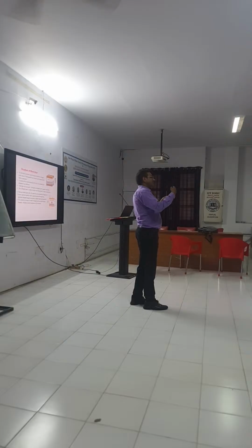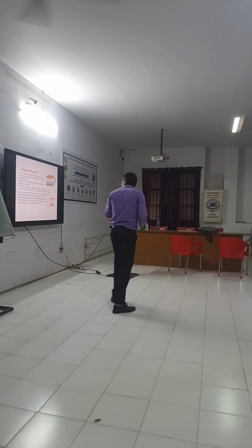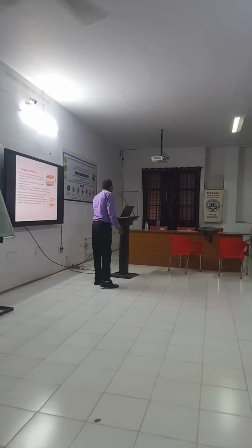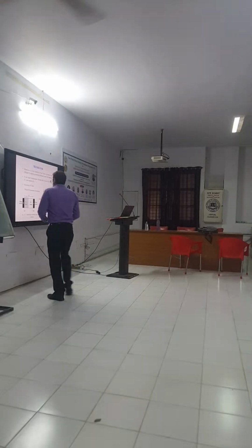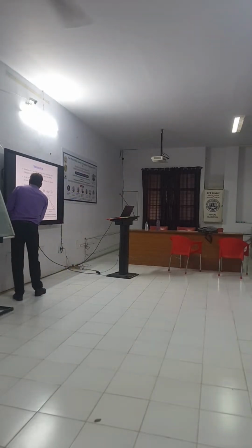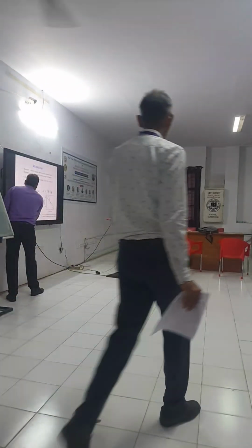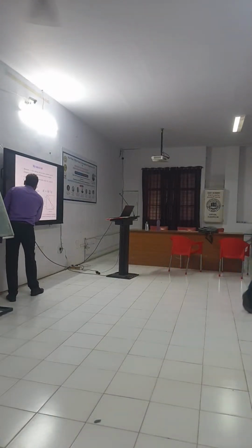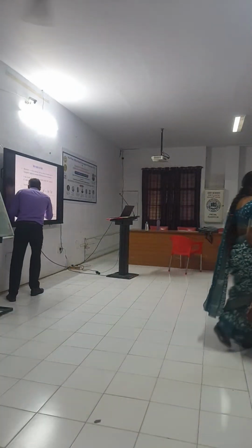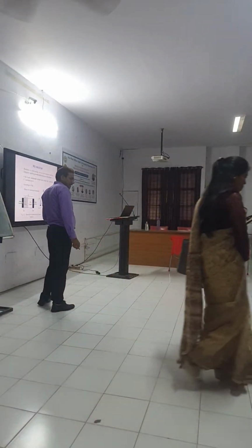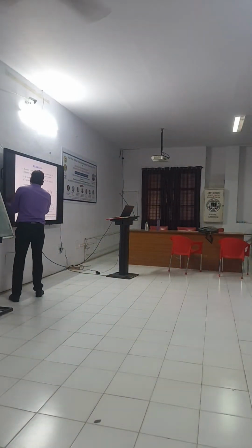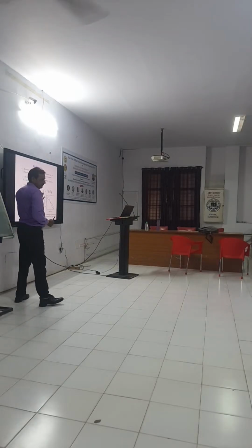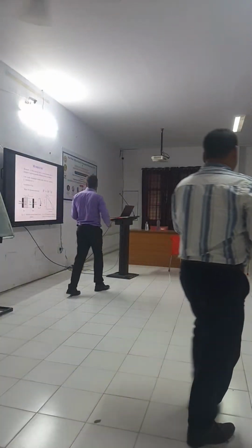With the applied potential, the doped region will increase, meaning the oxygen vacancies increase. When the doped region increases up to this, when W becomes D, it is a less resistive path. And when W becomes 0, it is highly resistive. It will act like that.